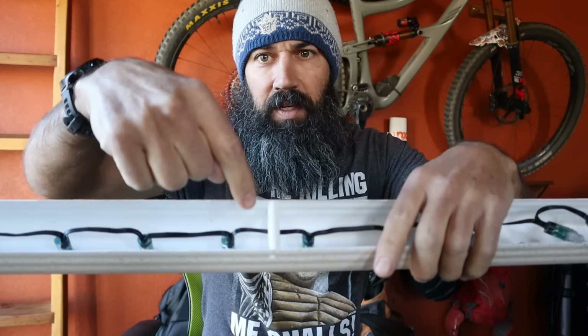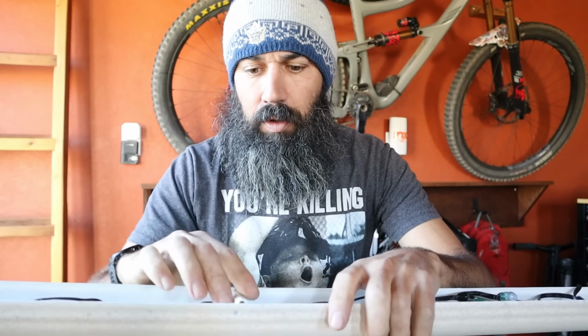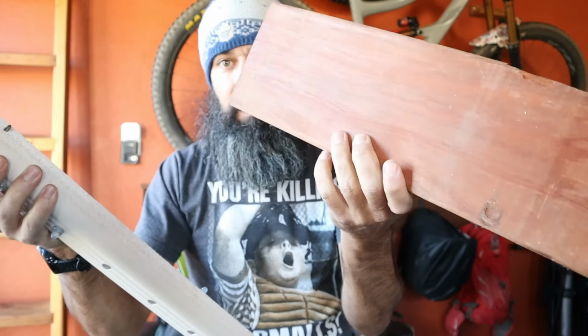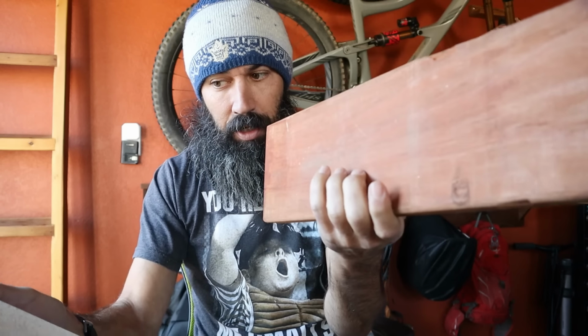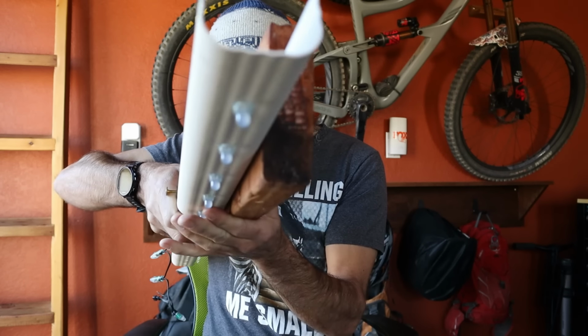I have it go over the top of my wiring, and then I have a screw. This one is 2 3/4 inch. I think a 3-inch would work fine in this case. And I basically have that screw go all the way through like that. So that's the part that's going to mount it to the back of my fascia. So let's pretend that this board is my fascia board and that this side is the back of the fascia. I would mount them like so.